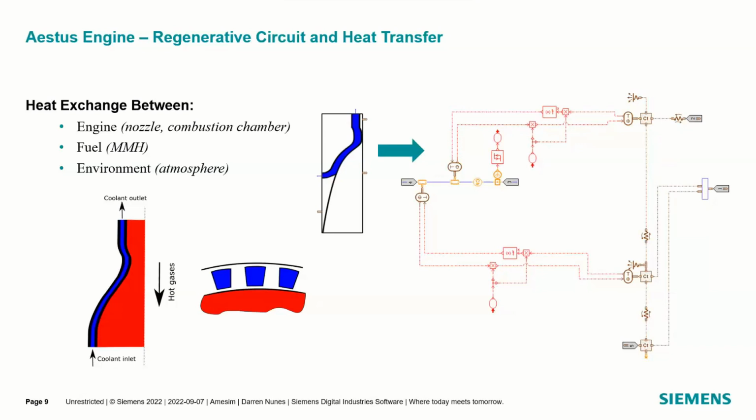And the heat exchange between the structure of the engine and the fuel is triggered by the fuel mass flow rate, right? And that's where you want this, in case of zero flow, when the engine starts or when it's shut down, we're modeling that heat exchange and how we can go into maybe some excessive fluid flow temperature, right? So we added in this first order lag to really not have any computational issues. But the propellant pressure we set to 17.7 bar A.